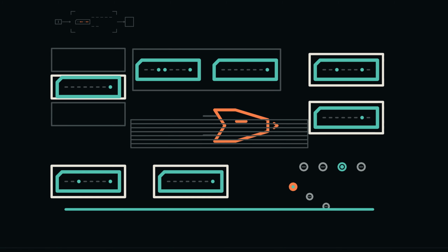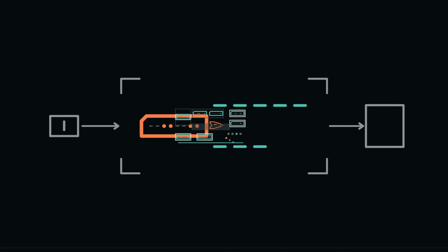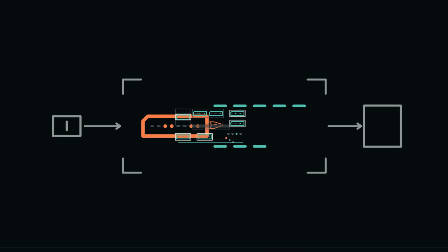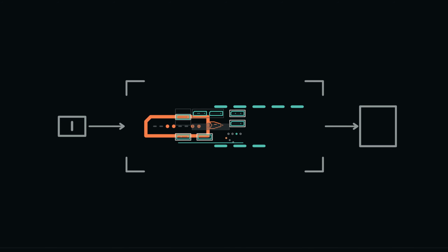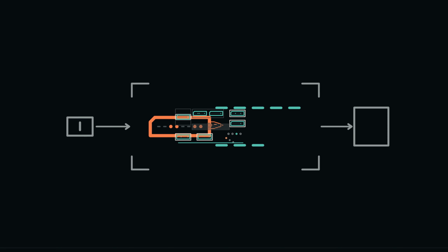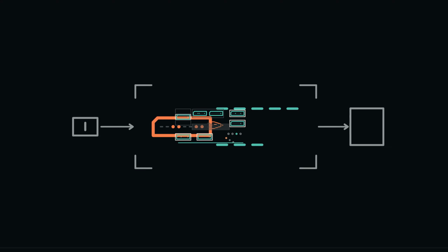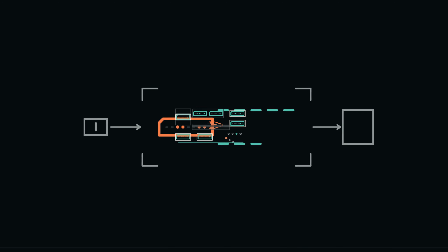Recompress the 7 edges into fetch, decode, execute, then reopen the state sequence once more. Fetch is 2 address read latch groups because SE8 instructions have 2 bytes. Decode interprets the latched fields and rejects illegal forms. Execute performs the specified transition and write back. PC supplies ordinary sequence, but its value is stored state and can therefore be changed. Flags preserve computed facts that control can inspect. That last connection gives the machine a new power. The next instruction can depend on a result. We can now turn a straight sequence into a loop without relying on an unexplained circular arrow.